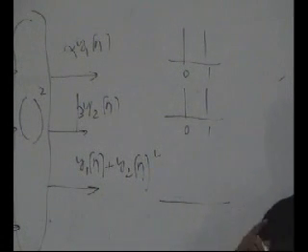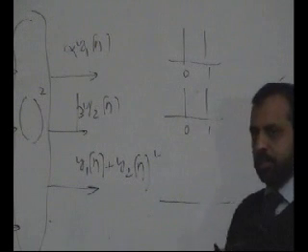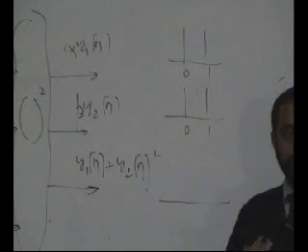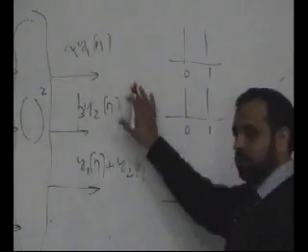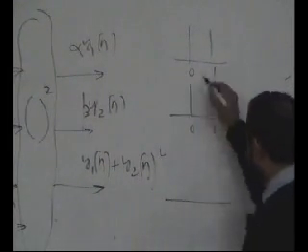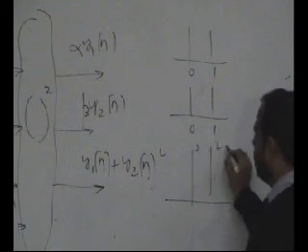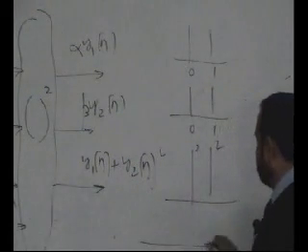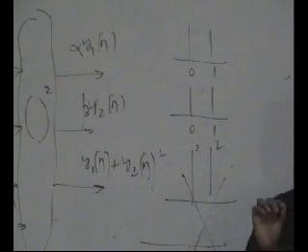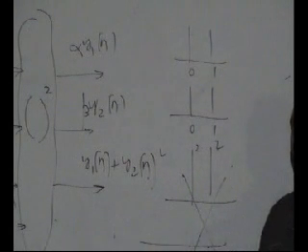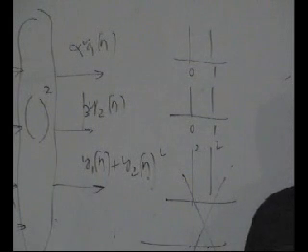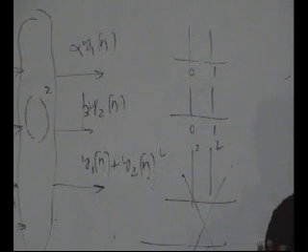So if you are applying individual inputs, you get individual outputs. If you add inputs together, and you're not getting the summation of the outputs, it means the system is not linear. Because this addition is giving you 2 2, and passing that to the system is giving you 0 0, they are not matching, which means the system is not a linear system. Right? Mostly our interest in signal processing, I should say 99% of the time, is dealing with only linear systems.